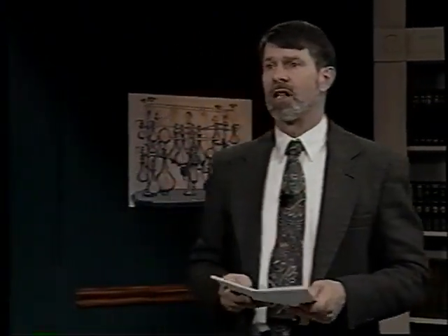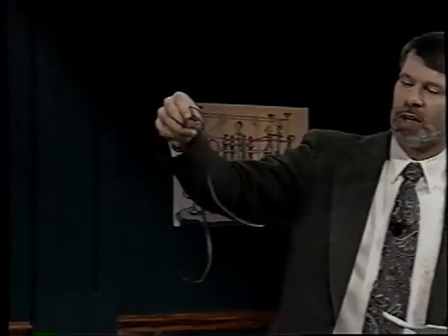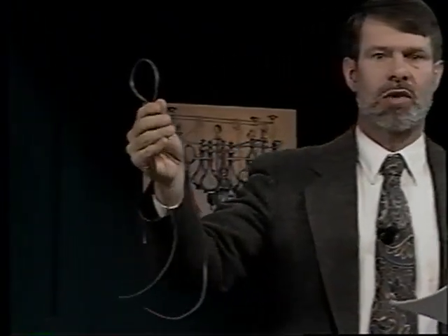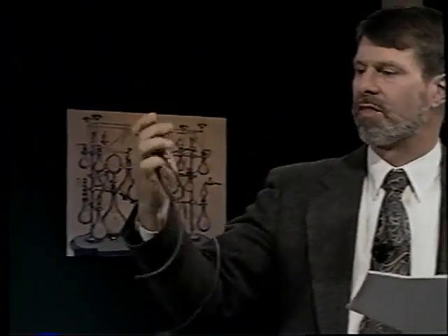The best insulators, as I think I've mentioned, are made from materials in which electrons don't move, things like ionically bonded materials. But the trouble is, most ionically bonded materials are very brittle. They don't make very good wires. So we compromise and use covalently bonded materials like plastics to wrap around the wires. Typical wire then will have a plastic coating around a metal core. And that's the way most wires are built. And they're amazingly flexible. You can tie wires in knots and crush them and abuse them in all sorts of ways, and they keep on working and working and working.